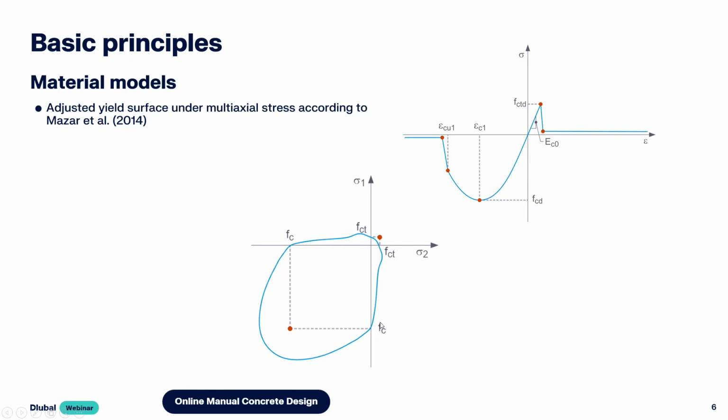In the biaxial tension region, so tension in both directions for an element, the strength of concrete is reduced. See here. As a result, the failure surface is reached at a lower stress. Crack formation follows. In the compression region, on the other hand, an increase in the permissible stress is required for elastic behavior, as shown here.